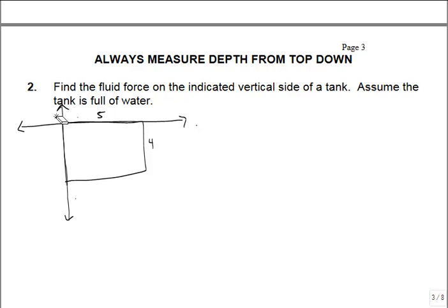And I'm going to draw in a little horizontal slice, which has a thickness of delta y. I would recommend labeling the top of your tank and the side point of your little slice here, because that vertical distance from here to here is going to be our h. And in order to figure out a function for that h, let's label our points.